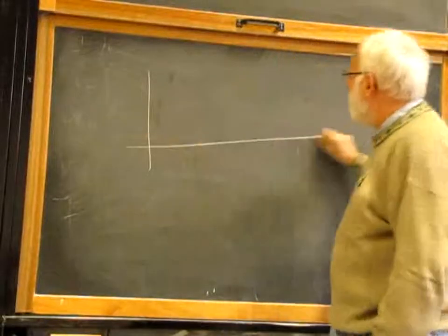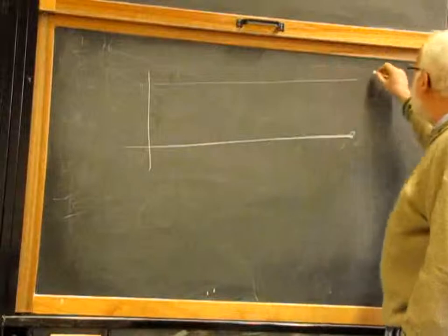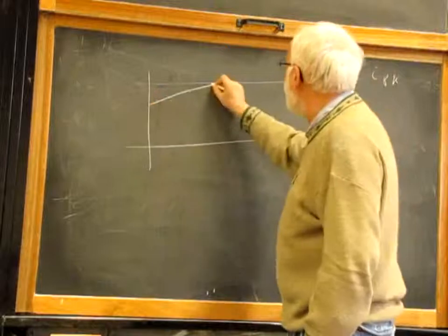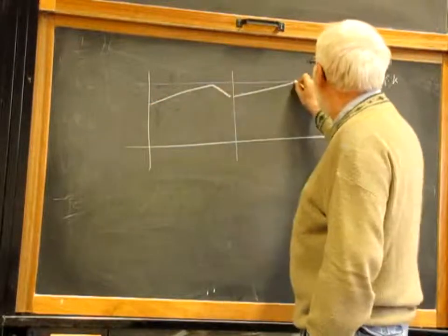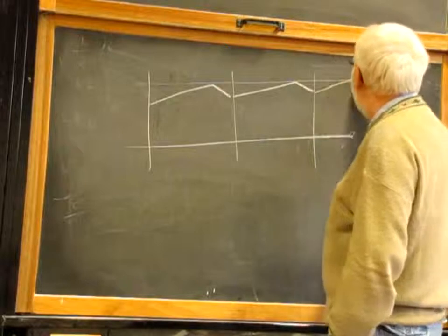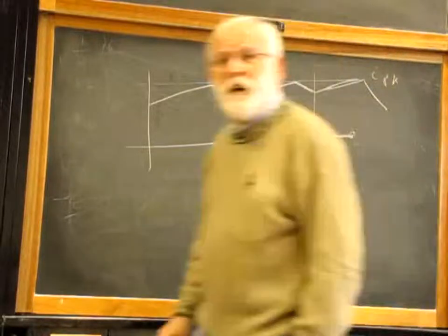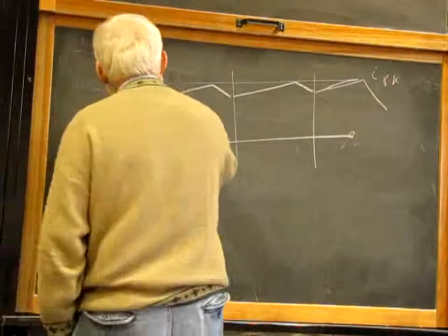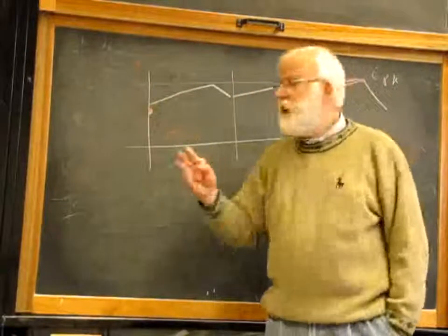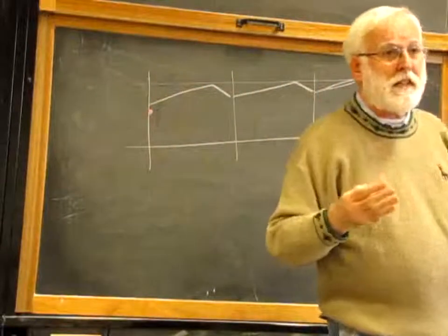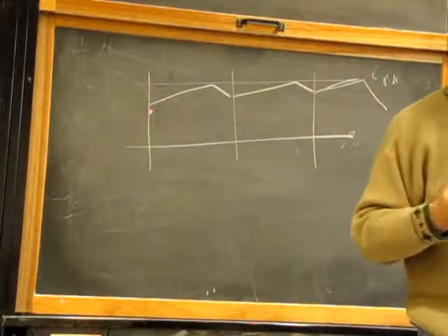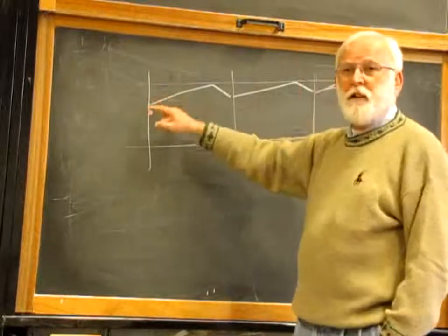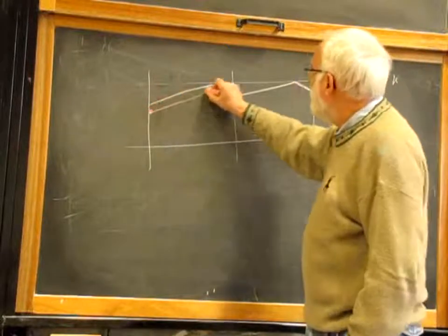is the subharmonic instability. Let's suppose that this is our I peak, and this is my IL. If a cycle starts with the wrong value of current, here for example, this is the initial value. Why? Because the previous cycle made some mistake. There was a noise that closed too early or opened too early the switch. So the next cycle will start with a current that is lower than it should be, and we have something like this.